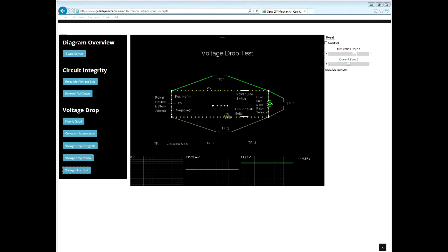Unfortunately, since automobile circuits are usually over an amp of current flow, continuity tests are not beneficial. This is because when a meter performs a continuity test, it does so by applying a very low voltage and low current. In a wire where every strand except one strand was destroyed, picture that in your mind. Big thick wire, but all of them got rubbed away except for one strand, it would show low resistance, because it's low voltage and low current, looking acceptable, yet could not allow high current to flow, being actually unacceptable.